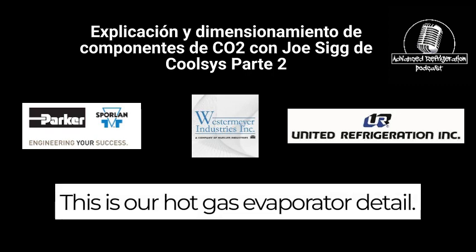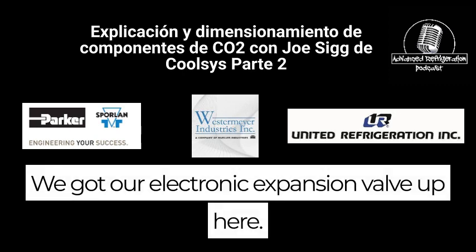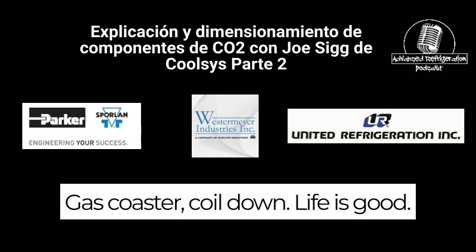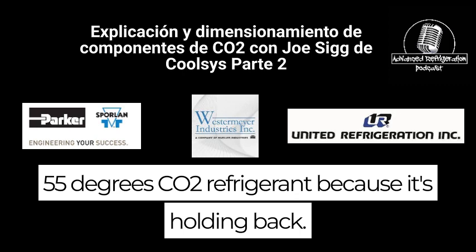This is just the last detail on our detail sheet. This is our hot gas evaporator detail. It kind of shows how the piping goes for a hot gas CO2 evaporator. We got our electronic expansion valve up here. Gas goes through the coil, down and out. Life is good. We got our defrost relief regulator here, set for 55 degrees CO2 refrigerant.